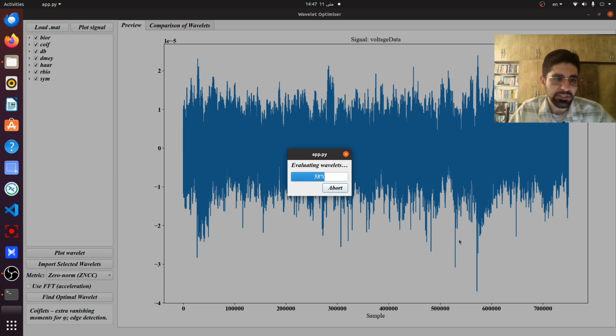In the cosine metric, the energy will be normalized, but the baseline won't change. The drifts won't change, because in some signals like speech signal processing, for the detection of emotions or some words, the signal has meaningful DC values, and we are not interested in removing those DC values. But the energy will be normalized, so the sigma won't have much effect on the signal.